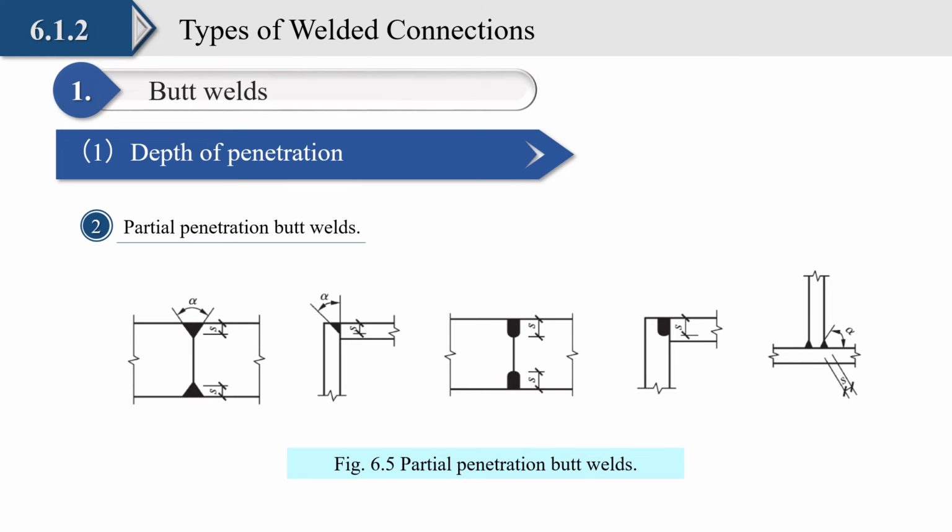The butt welds may require extensive edge penetration as well as precise fabrication, and as a result, are more costly. Therefore, if possible, butt welds should be avoided because of their high cost compared with fillet welds.